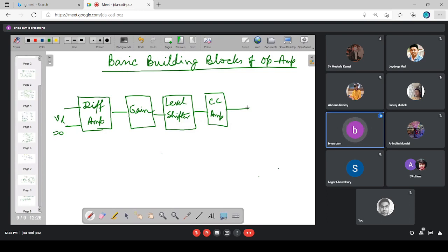It tries to function with those designed parameters, but as those parameters are no longer at the same level as the designed parameter levels, the level shifter is not able to give the proper functionality. So the level shifter cannot help it because it has already been designed and fabricated.